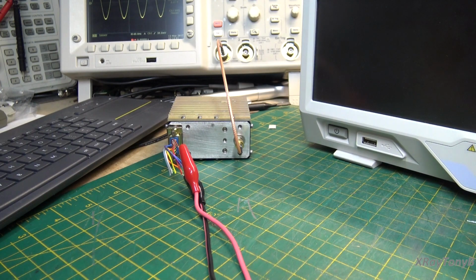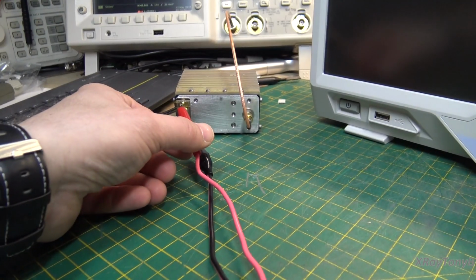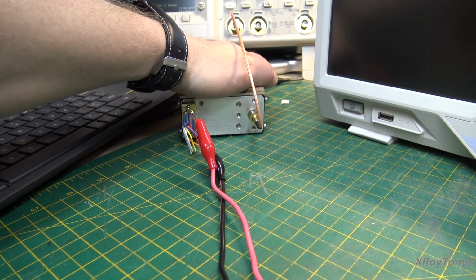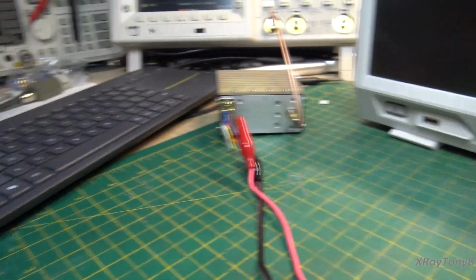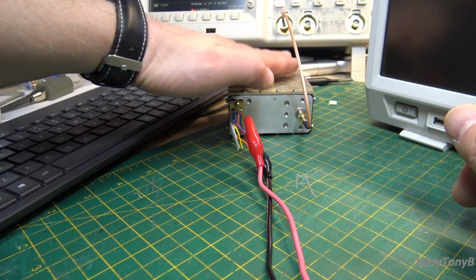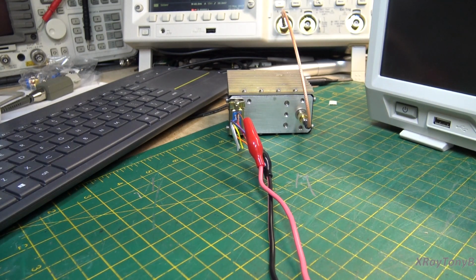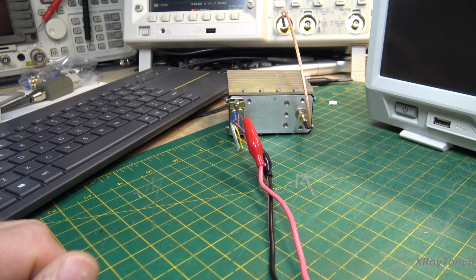So really what we're going to do today is, you can see it works. I just have a power supply clipped into it right now, but this heat sink is not adequate for this. These get very warm, and the longer they're on, the hotter they get. And you really want to keep these at an operating temperature of around 50 degrees C, no more. And you do want them to be warm, because the heat is where they get accurate, but you don't want them to overheat, because it actually will shorten the life of the device. If these are kept at a good temperature, they will last a very long time.